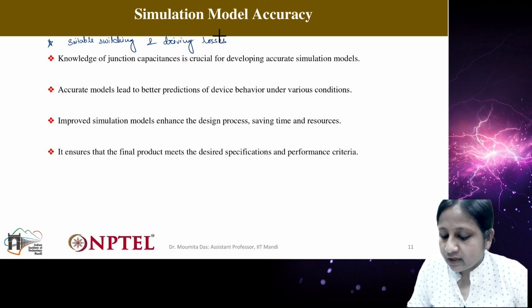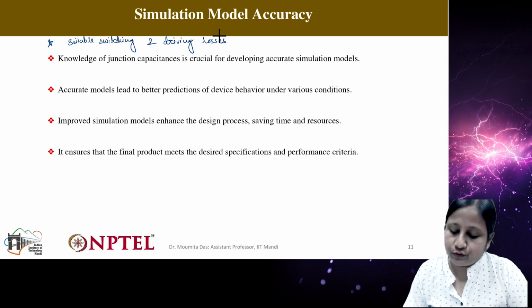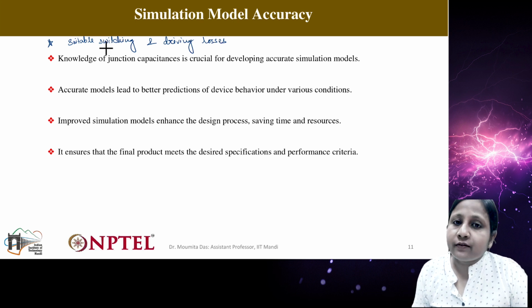In order to find suitable switching or driving losses, we need these capacitance values. So this is the first advantage of characterizing these capacitances.